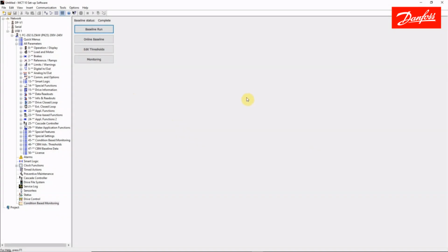Getting back to our demonstration today, we're going to choose the quick baseline run and sweep the speed spectrum in a modest 1-minute interval. That's the quickest that we can collect the data throughout the speed range in question. Once we've made this selection, we'll press the next button. This will take us to the vibration setups. Up to 2 channels are available.